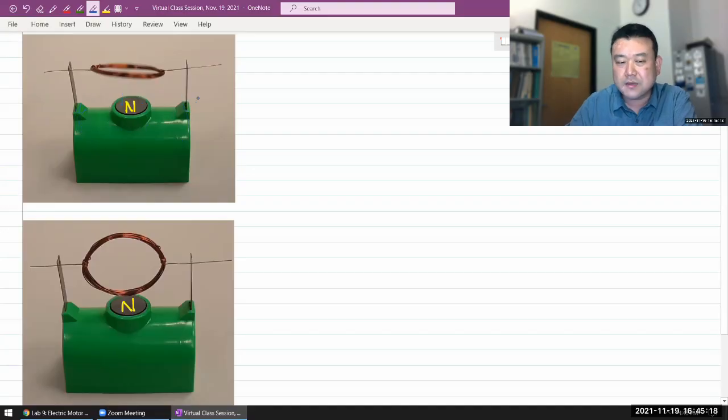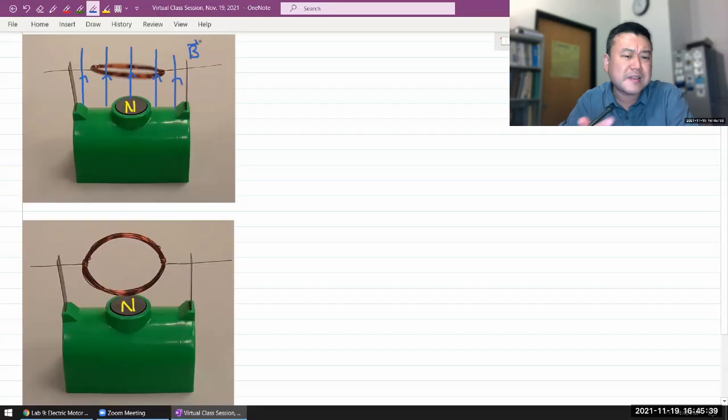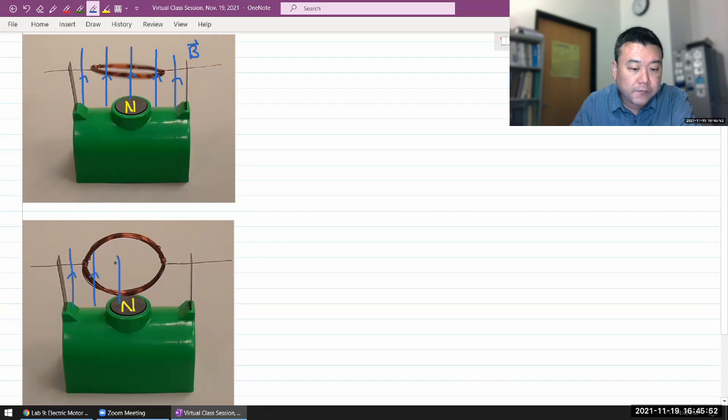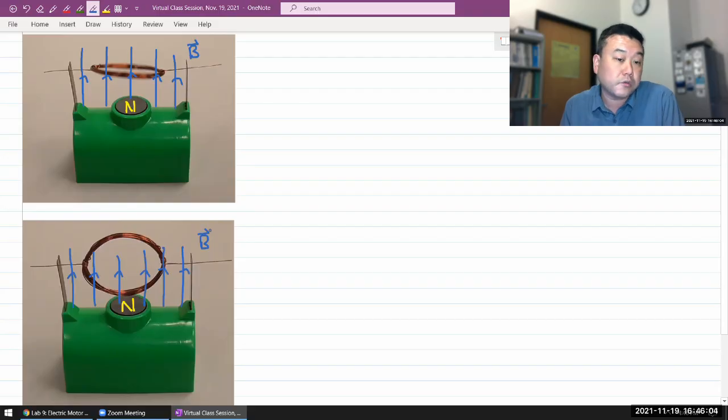But for the purpose of discussion, let's just suppose that we have a region of uniform-ish magnetic field over the entire current carrying coil. Again, this is not quite realistic, and that's not how the actual physical demo is set up. But for the purpose of talking about what's happening with a motor, all we need is a uniform magnetic field. We don't need a dipole field or some spatially varying component. Nothing like that is necessary. So I'll just describe a uniform magnetic field, the simplest setup that we need for this motor to work. In the simplest illustration, we can model the current as a single loop of current.